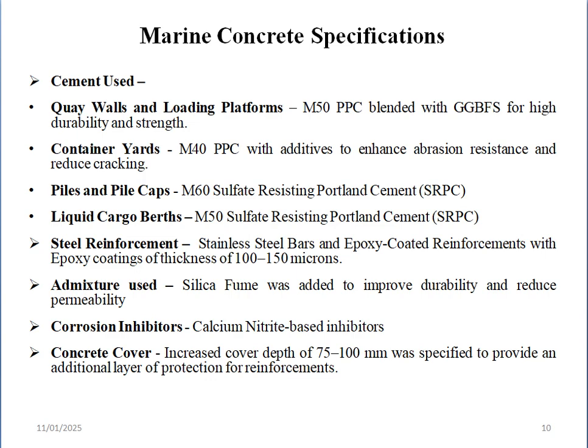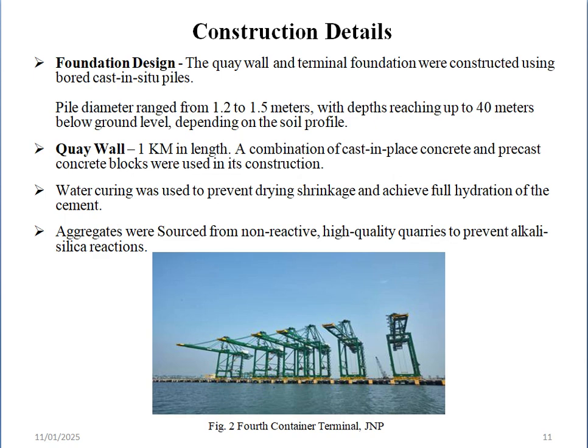Admixture use: silica fume was added to improve durability and reduce permeability. Corrosion inhibitors: calcium nitrite based inhibitors were used. Concrete cover. Increased cover depth of 75 to 100 mm was specified to provide an additional layer of protection for reinforcements. Construction details. Foundation design.